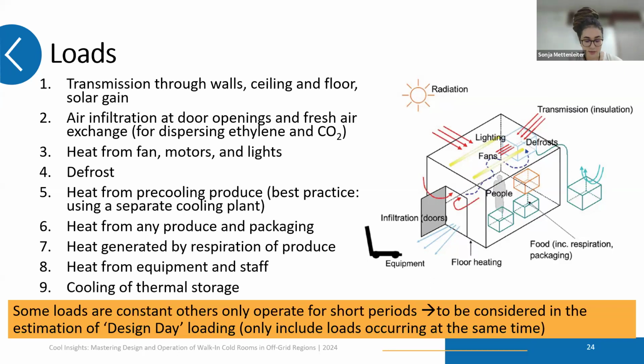The design day is basically a compromise, a balance of the cooling demand and the cooling profile set somewhere above the average day and the typical demand, and the cooling capacity of the refrigeration system must then also match the heat load. Otherwise, you have spoilage of the produce. Next slide.